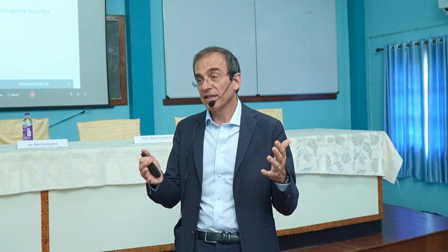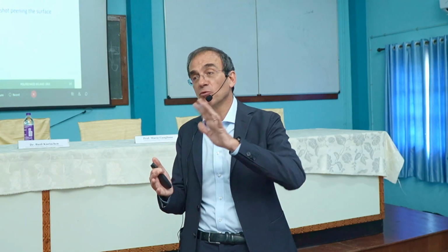Sir, regarding the measurement of the residual stresses, what kind of method have you followed? For measurement, indeed, there are many methods. I'm using XRD, X-ray diffraction, the diffractometer. Today the diffractometer is always seen as just a lab facility used for small parts, but there are now many equipment where the part is fixed and it is the tube and the detector that move with respect to the part.